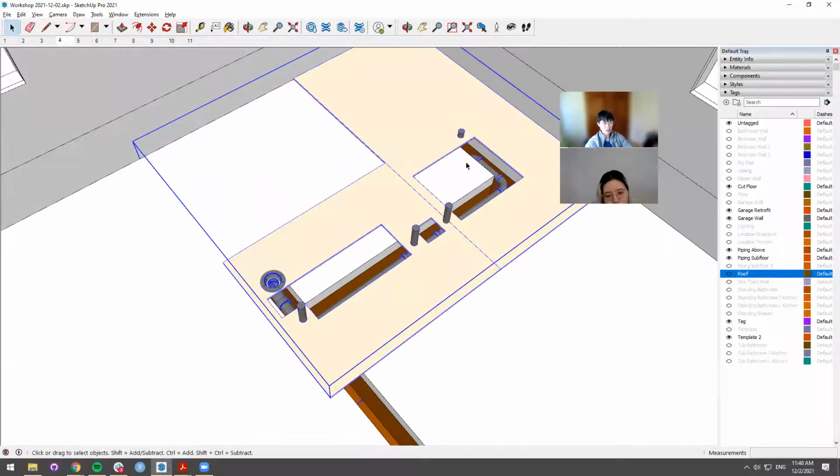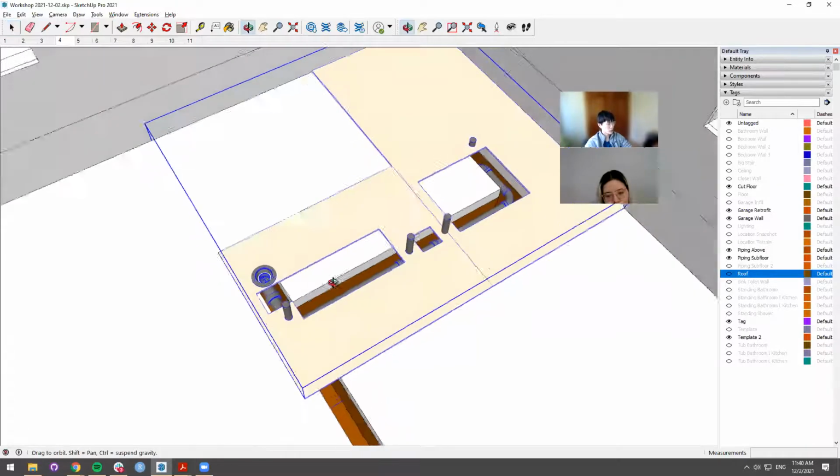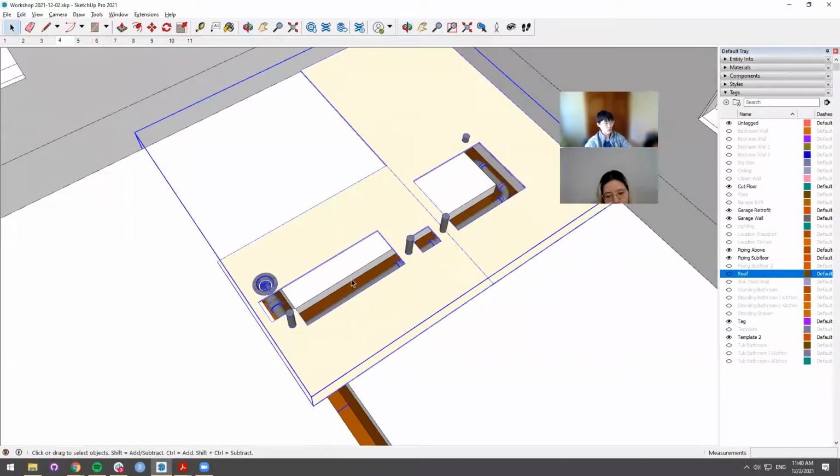You can then fill in aggregate and pour the concrete with the plywood there, keeping this thing exactly in place as long as you need to, and then you can remove the plywood at some point. But that would allow for this subfloor plumbing to be where it needs to be.